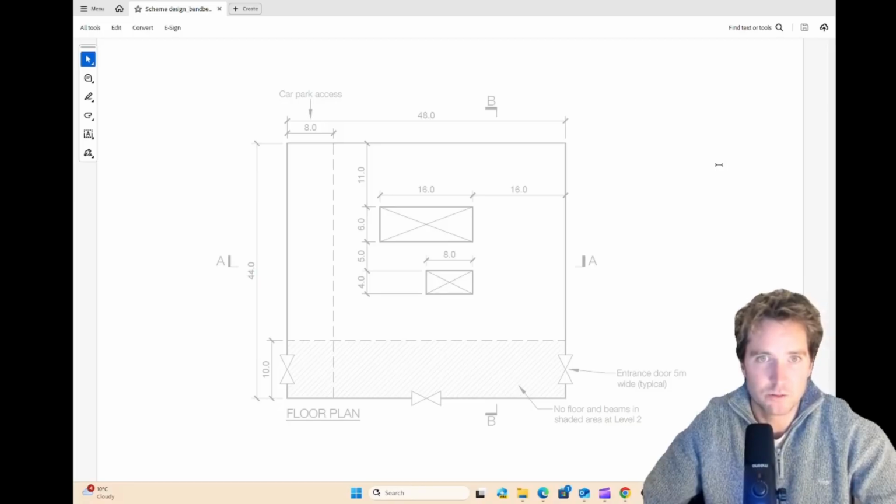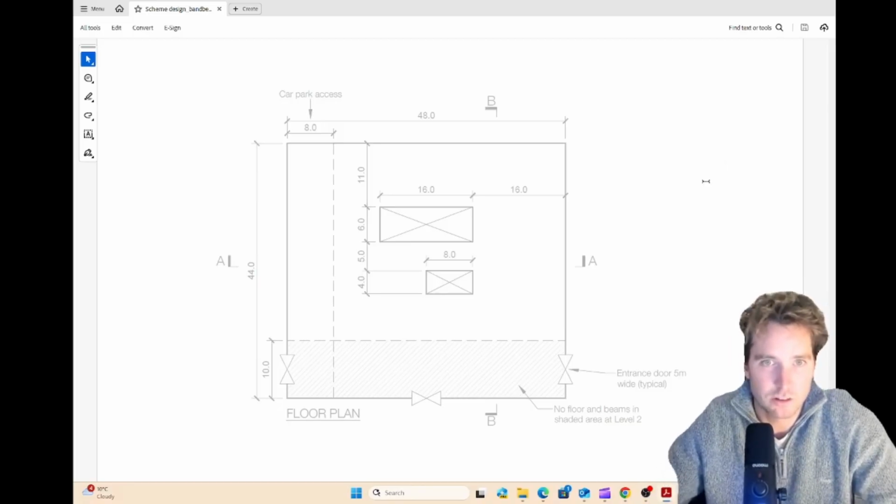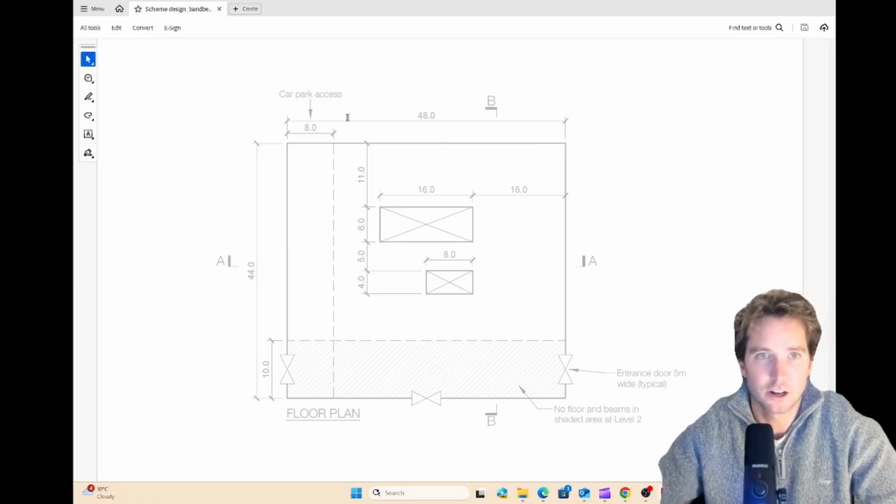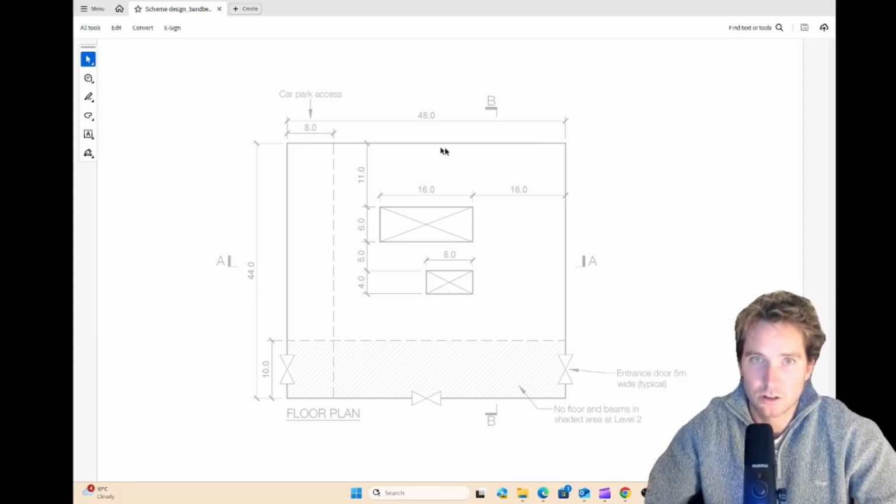So that's essentially another limitation that we need to understand when we're putting our grids together. So now we understand our limitations. We've chosen our floor type, the PT one-way slab with band beams. Now it's our time to put grids together. So I like to use something that divides nicely the full length of the building. So 48, I'm going to go grids at 8 meter centers across the page here.